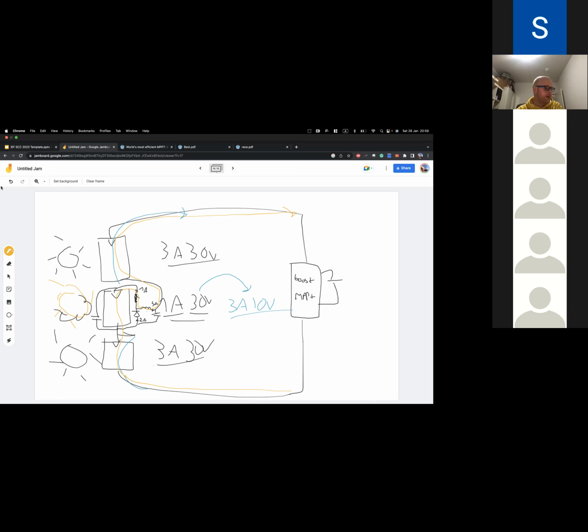They already exist, right? But not for solar car. Right. Okay. I get it. Thank you. Yeah, I think it makes sense. And then rather than 0 volts, with a normal diode you have a negative voltage. With a perfect diode, you have 0 volt. And then with this buck converter, you actually get some useful voltage where you can actually get some positive power out. Yeah. Right.